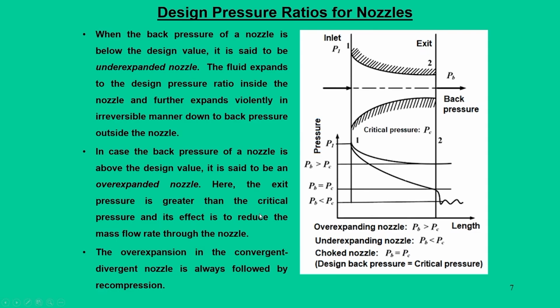Okay. Now, let us understand more details of the practical utility, how these nozzles are normally operated. In fact, when you design this nozzle, we have two conditions. One is the area information, because the minimum area will give you the choke conditions. At the same time, the other parameter that regulates the flow is the pressure ratio or pressure difference across this nozzle.